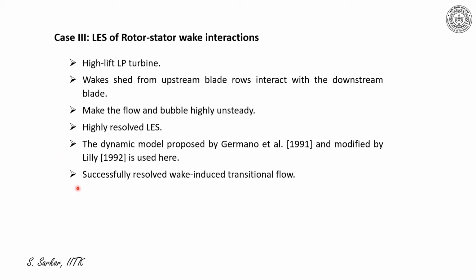The approach was successful in resolving wake-induced transition. It has illustrated the periodic wake as it passes over a turbine blade, inducing an unsteady environment where the transition is multimodal. Multimodal transition means that different modes of transition can coexist at different parts of the blade passage, which appears very complex, and this complex environment has been successfully resolved by the ALES.